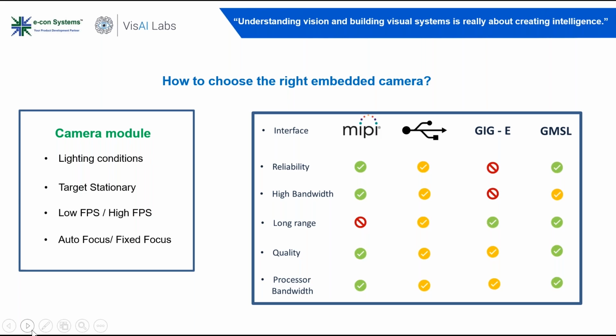Also, if the use case requires a color camera, make sure to choose a camera module with an image signal processor. The image signal processor is the one responsible for auto functions. Adapting to different lighting and accurate color reproduction is a key thing, and without an image signal processor, it is going to be really tough. So consider these points before choosing the camera module.